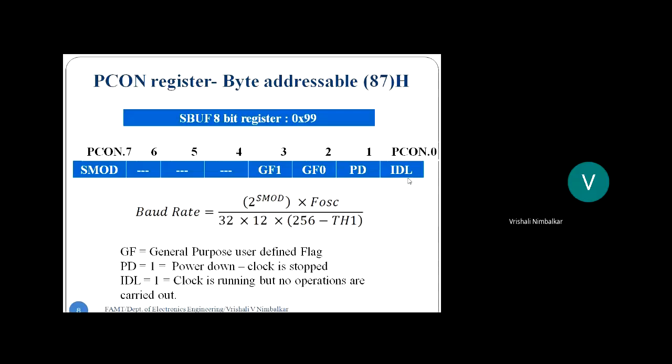When the CPU stops working, there is no execution going on, there is no data transfer going on. So whenever there is no data transfer, there is no logic 0, logic 1 flowing in the circuit, meaning there is no current flow, so there will be no power dissipation or lesser power dissipation. So that is what idle mode is.